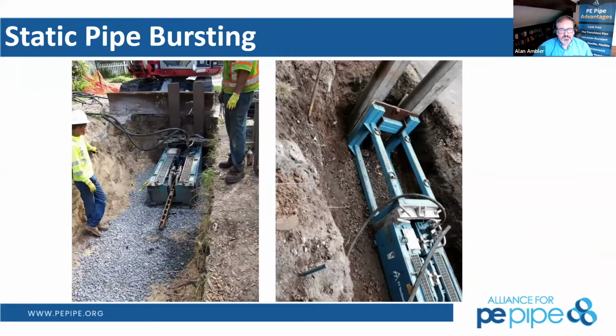So static pipe bursting. This is why sometimes when I talk about pipe bursting, I use the term surgical excavation as we go through neighborhoods, as some of these entrance and exit pits for even the machinery as we get aligned through this can be very, very small. And that excavation then, of course, directly relates to reduced restoration in a suburban or urban environment. That could be a fairly significant amount of cost savings for projects as we move through.